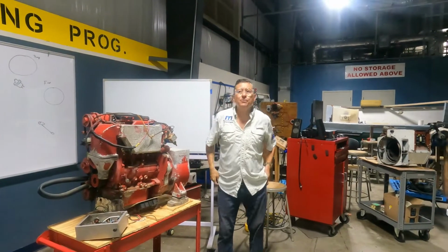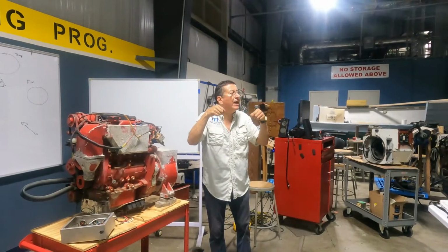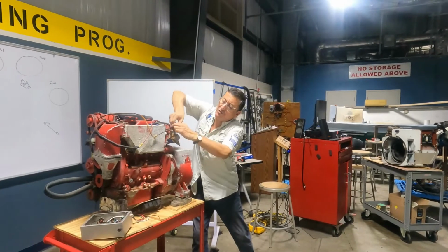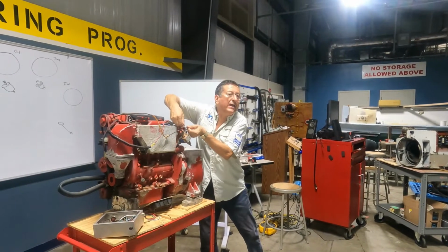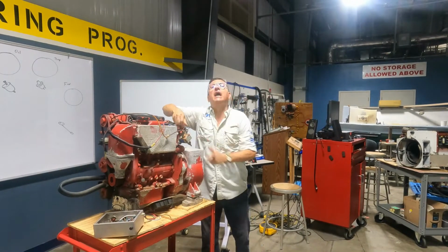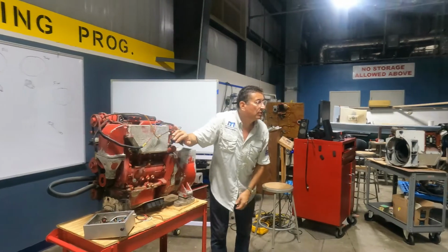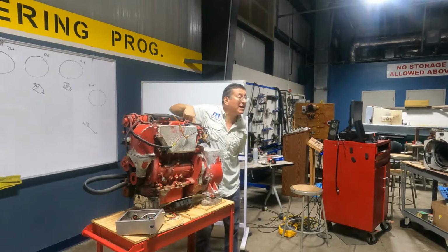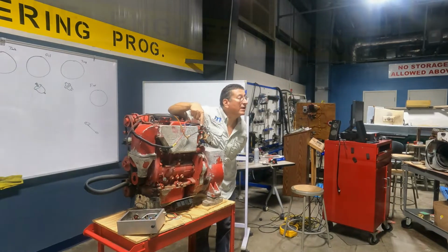Okay, my friend, can you prepare a couple of alligator cables? Positive and negative directly. Disconnect the positive, disconnect the negative, bring power here. Oh, now it's working. Okay. The pump is good. But the signal is not coming from the relay. You see the relay? Into here.